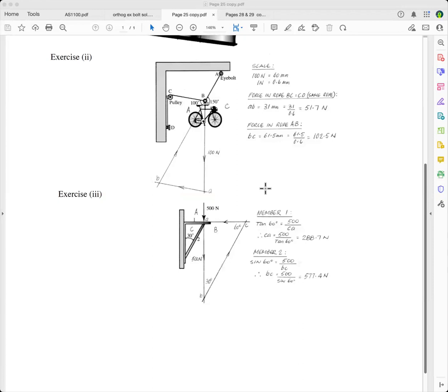And then we have to leave that, and then we come to the next force, which is CA. And we know that it's got to go through A there. And so you just produce it on where it hits this other force. There's your point of concurrence of these 2 forces. And so that will be BC. And you know that these arrows, the senses, are directed by this force here.